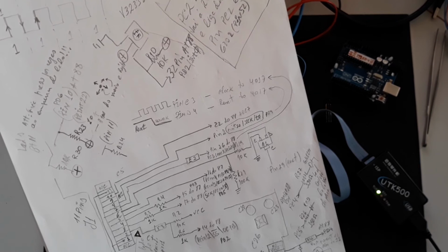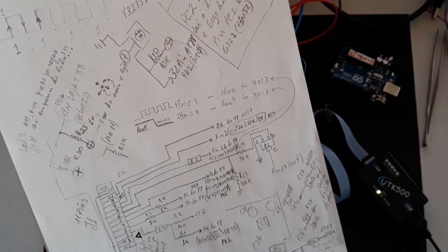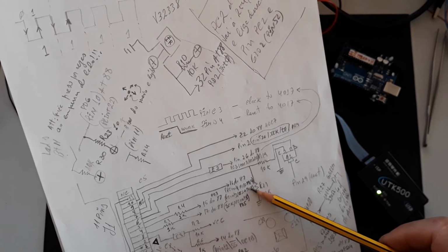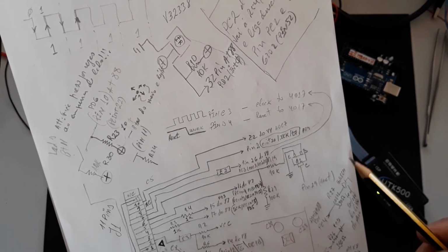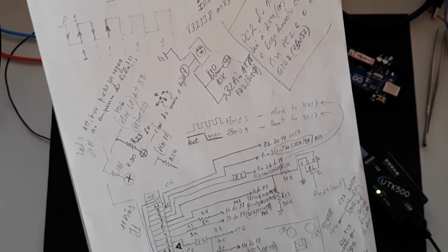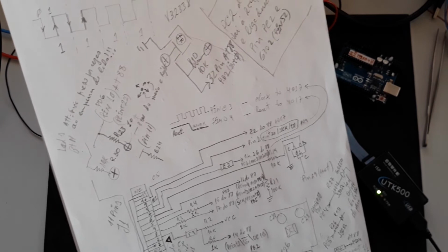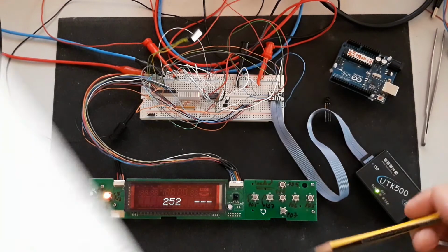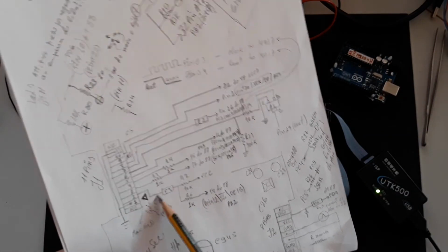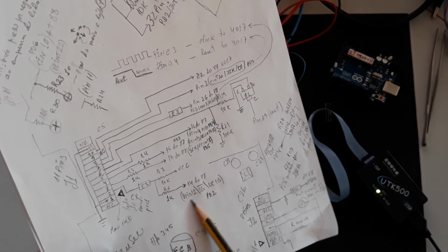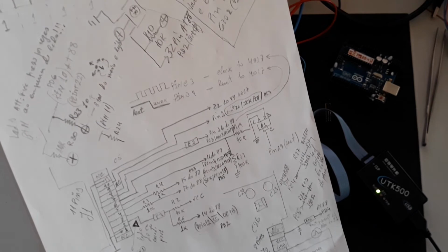Don't forget, okay? This is the pin reset, SCK, MISO, MOSI, and these are the 4 signals to program the ATmega8, okay? Here the PB2 is controlling the interrupt, okay? If you connect this point to the GND, you start the interrupt related to the PCINT2, okay?